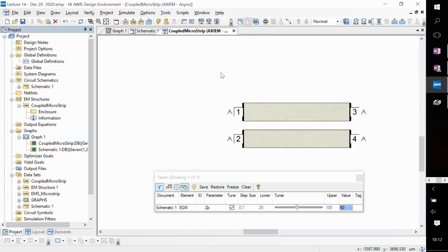When we are setting up an even mode gamma measurement like this, what it's actually doing is sending an excitation simultaneously to both 1 and 2, in phase. This phase relationship is very important, because otherwise V1 plus V2 and V1 minus V2 completely lose their meaning.